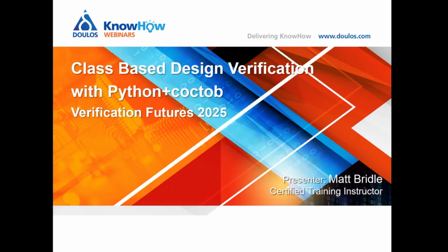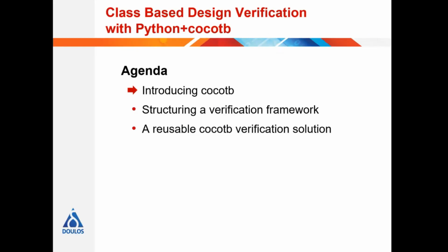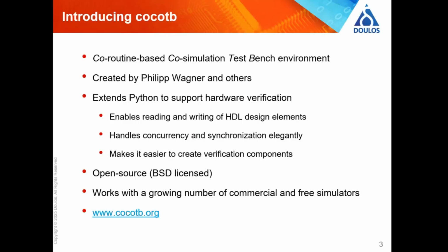I'm going to be talking about Cocotb, and I'll just give you first a little rundown on what Cocotb is. It stands for coroutine based co-simulation test bench environment, created by Philippe Wagner and others. The idea is that it's based on Python and it uses Python to do hardware verification. And obviously there's some stuff that needs to be added to Python to make that work.